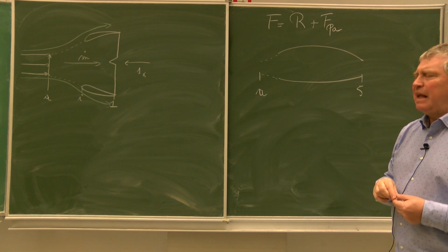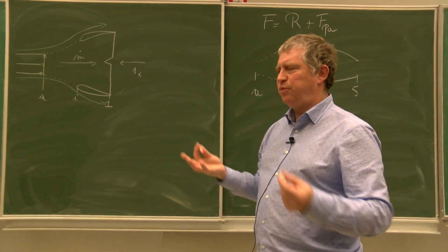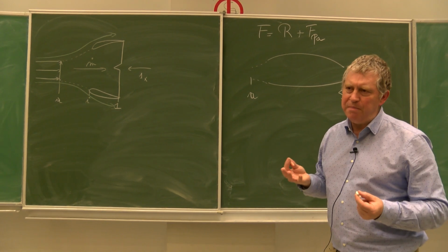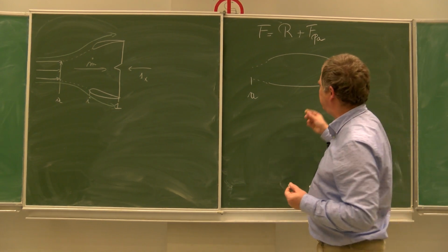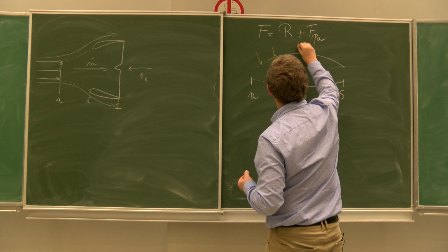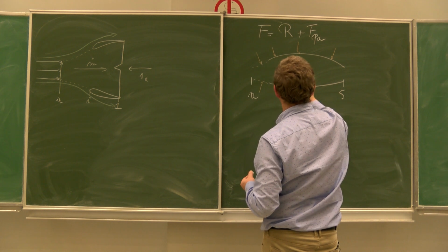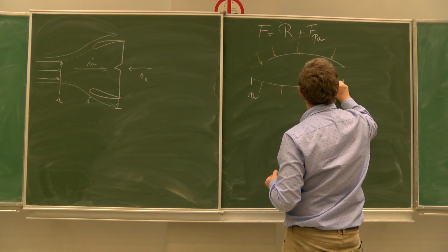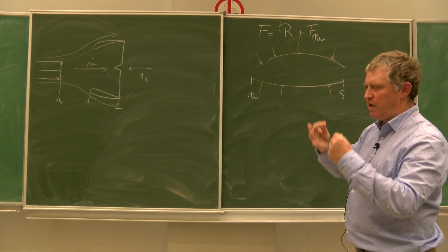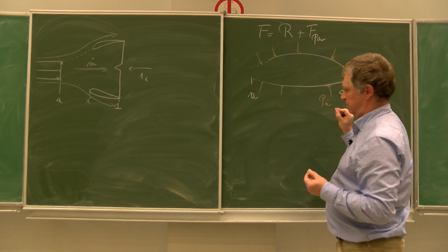And that means that in this definition, this is a choice that we have made. You could take another one, but you would then have other problems. There will be a problem at a certain moment. You are considering that everywhere the external pressure acting on the stream tube and acting on the external side, always perpendicular to the nacelle, to the walls, to the external cowl of the engine, is PA everywhere.